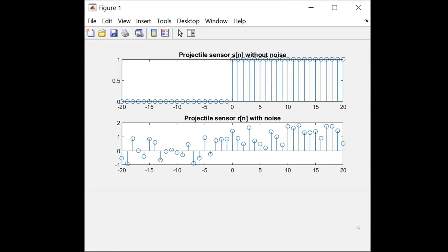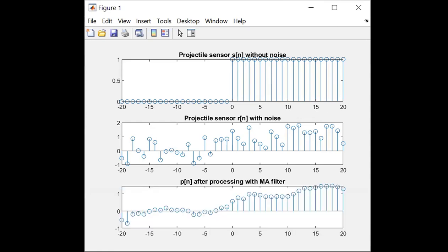If you put it through that moving average filter that I just showed, this is the actual data again. Now it's pretty clear that these random data, half the time will be high, half the time will be low. So when you process it, now you could create a threshold at say the 0.5 level and be far more confident that you're actually going to detonate it at the right location. If you put the threshold 0.5 level over here, you'd pre-detonate because of noise. Questions on that?